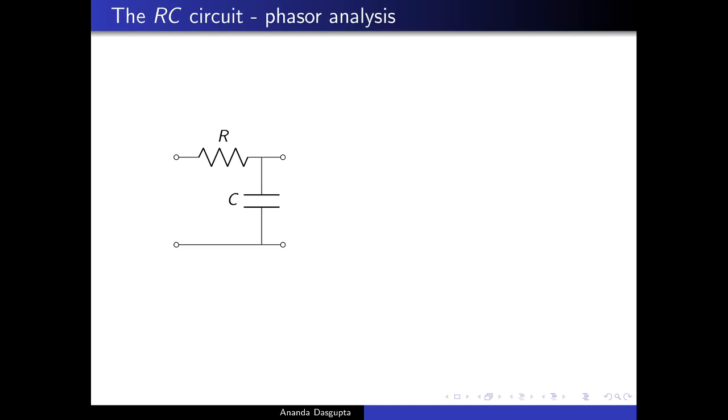Now, if we use this idea for our RC circuit, we have just drawn the RC circuit slightly differently. This form just emphasizes that we want the voltage across the capacitor to be the output of our circuit. But notice that if we think of the current as a complex valued function, we can draw the current both as a point on the complex plane or as a vector joining the origin to that point. Then, if the current is a complex number, which in this case I have just indicated as a horizontal line, so maybe at some particular time t the current just is real, when the total phase is 0 at that instant of time, then the voltage across the resistance is simply going to be R times that, R being a real number, a complex vector indicating that complex number in the same direction.